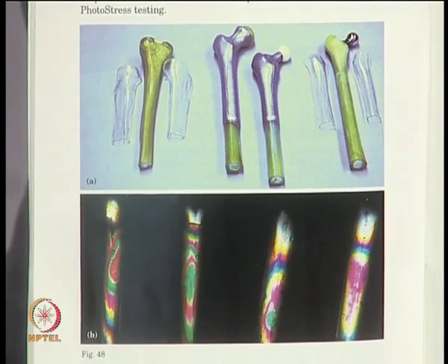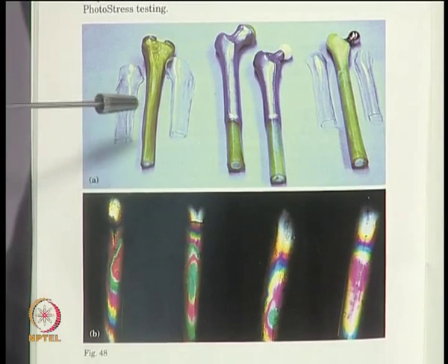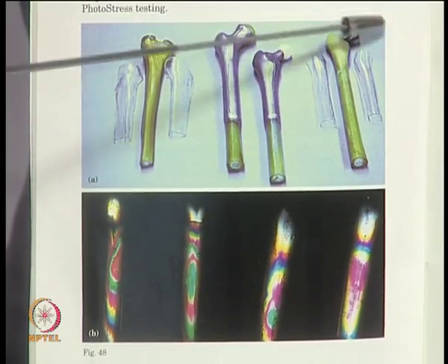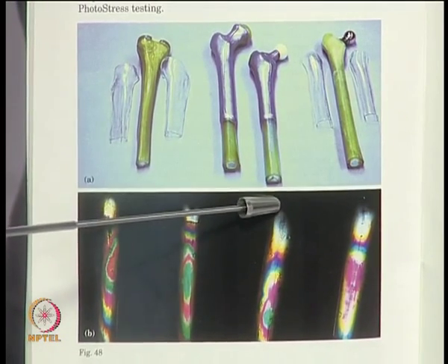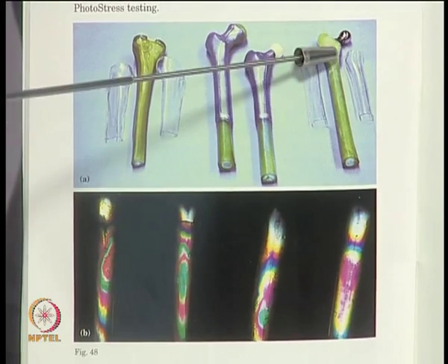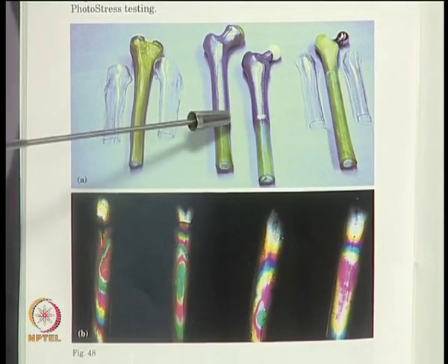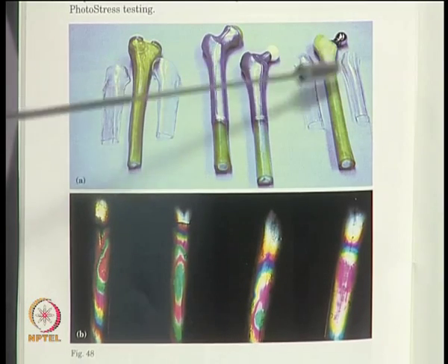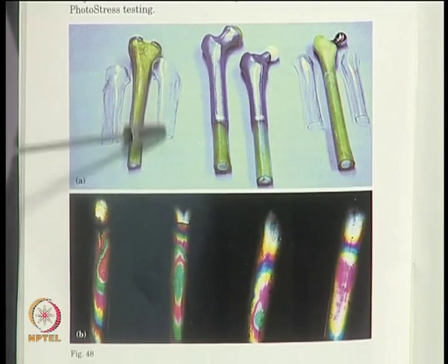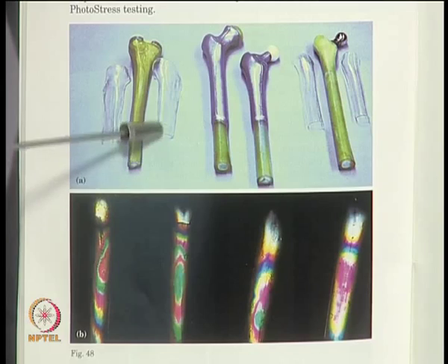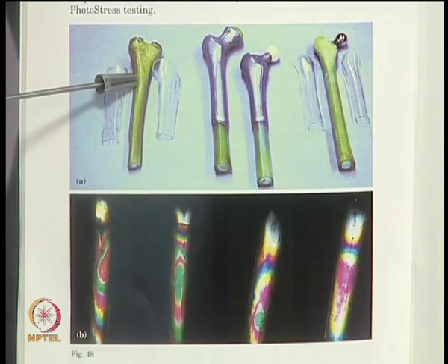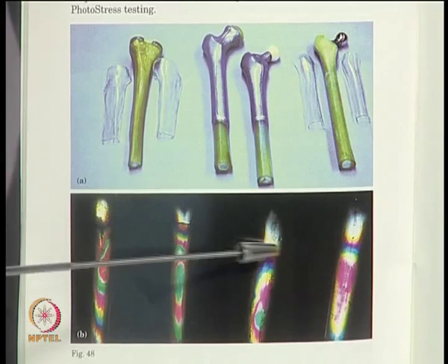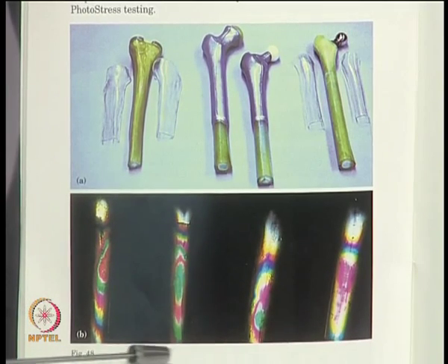This shows another example of application of photoelastic coating, and here it is for a prosthesis example, where you have hip replacement and you want to analyze what is the influence of these implants. You have a shell which is made by contourable plastic, which is bonded onto the bone, and these are all the respective fringe patterns obtained for various configurations.